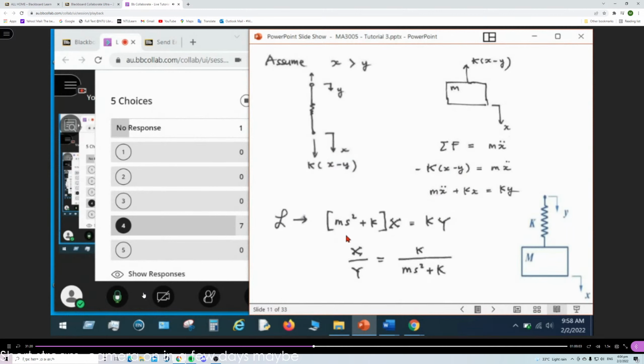So now the last step. We perform the Laplace transform. As I mentioned, you can see the table. You can follow the lecturer or follow me to do it this way. This is the M here. x double dot, if you take the Laplace transform, you get s squared multiplied by X, the capital letter X. And then for kx, you get k multiplied by X.